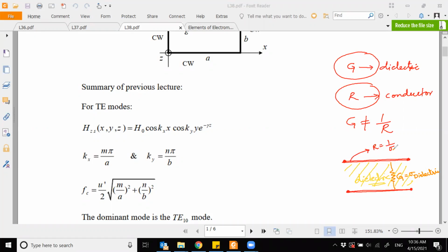And this is for the conductor. I have emphasized this several times, and that's why we put a resistor here, and this resistor is R. The conductance is different and R is different. Just logically think, when we are defining the transmission line parameters, why are we defining G and R separately? If G becomes 1 over R, which was your poll question, then why would I keep G and R separate besides L and C as the transmission line parameters? If they are equal, I will not put that, right?